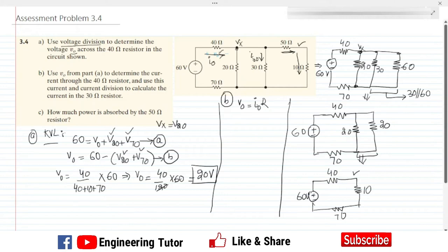If any two of those values are known, we can easily find the third value. So here, as we know V0 and R, we can easily find I0. The I0 value is V0 divided by R. Putting values here, that is 20 by 40, so this is now 0.5 ampere. So the value of total current is 0.5 amperes.